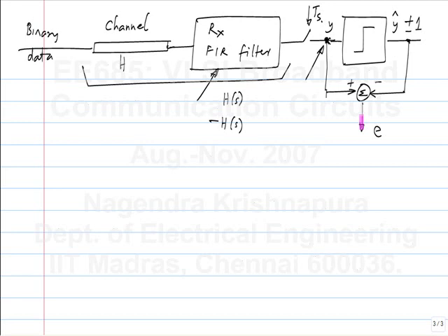Suppose that y will get plus 1. So that data will pass to that comparator. So there will be a delay. Let's assume there is no delay here. It's sampled data, right? So you are operating only on the samples, so the delay through this doesn't matter, because I just want the difference between this number and this number. I have one clock period to process that. Like every digital circuit has a delay, but that doesn't mean if you make an adder, the output result will be wrong. It will just come after some delay.